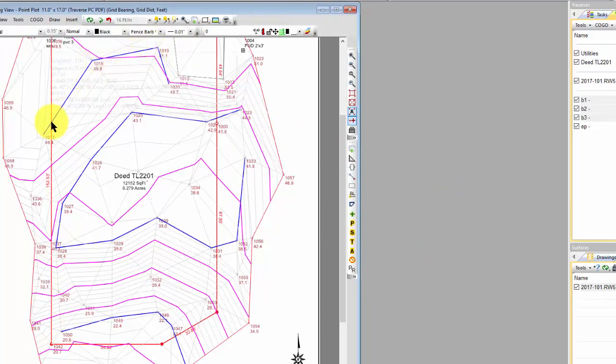as it's got break lines right here, break lines here, and really all I'm doing, I'm picking up the top of a slope, the toe of a slope. Here I've got the toe of this slope, the top of this slope, and that kind of further defines this little bit of a bench in here.